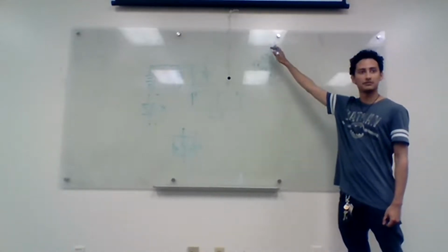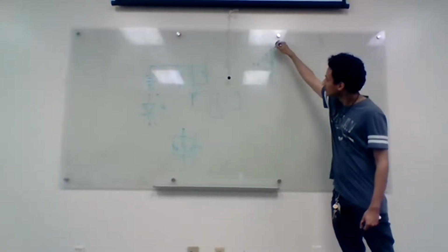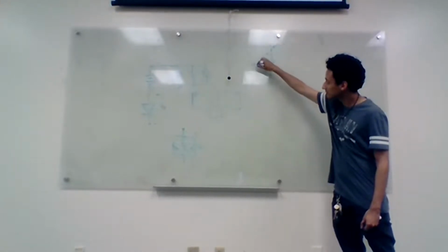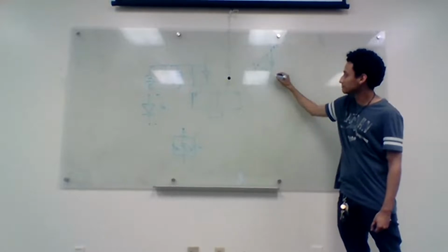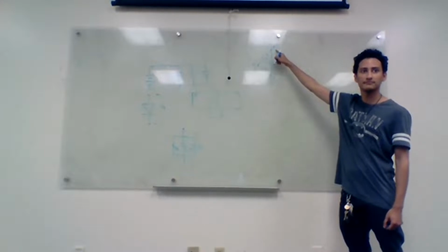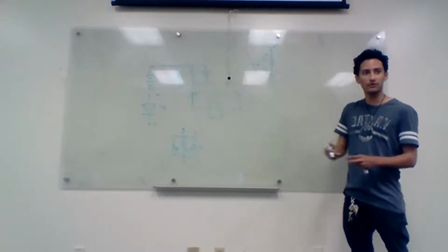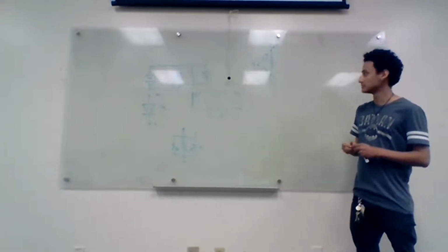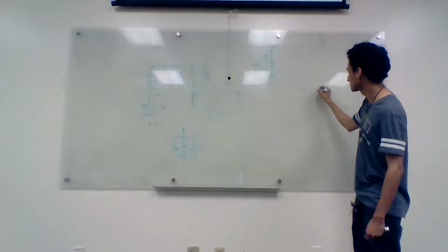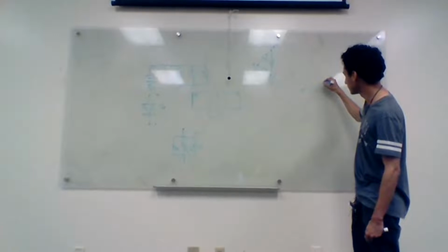We're operating in the forward region, so this diode is reverse biased. This voltage is the highest point. This is higher than the emitter, but less so than the collector. So this is reverse bias. This one's forward bias. That's your forward operating region. So if you do the small signal model for that, between the base and the collector, you just have C sub J.